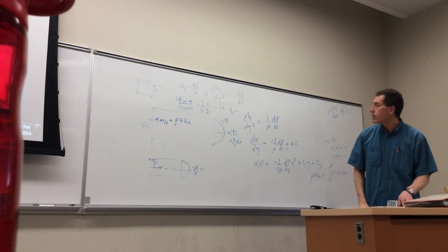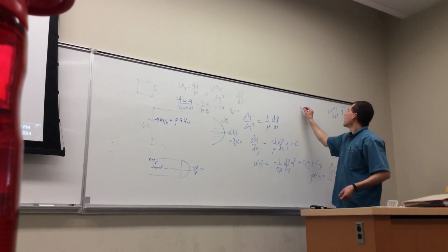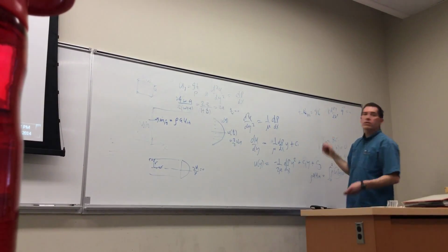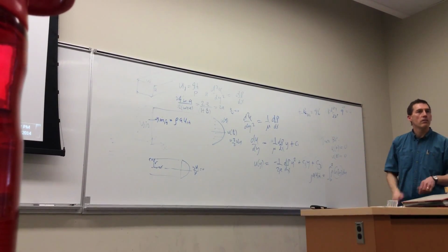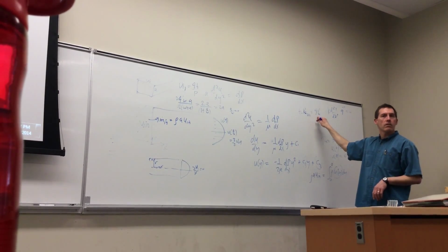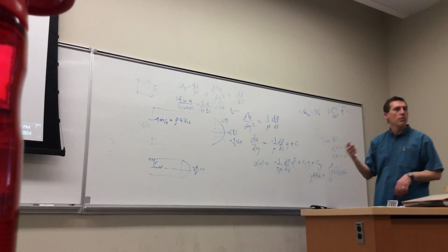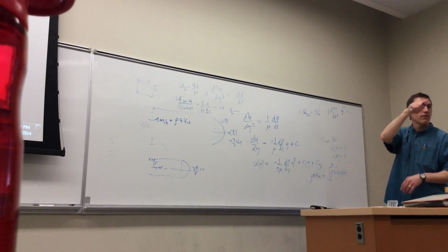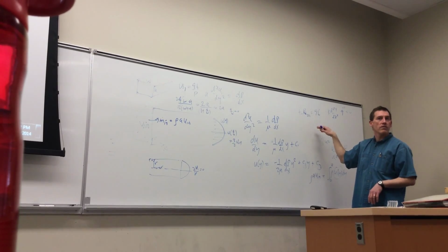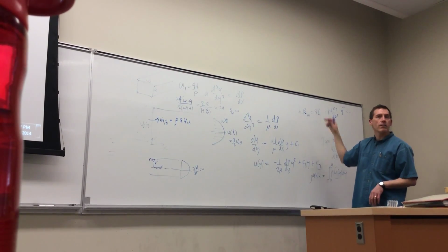The friction factor times Reynolds number based on the hydraulic diameter should be 96 for parallel plates. It's equal to 64 for the circular tube, right? That's in the Moody diagram. It shows friction factor equals 64 over Reynolds for the circular tube, so I think it's 96 for parallel plates.